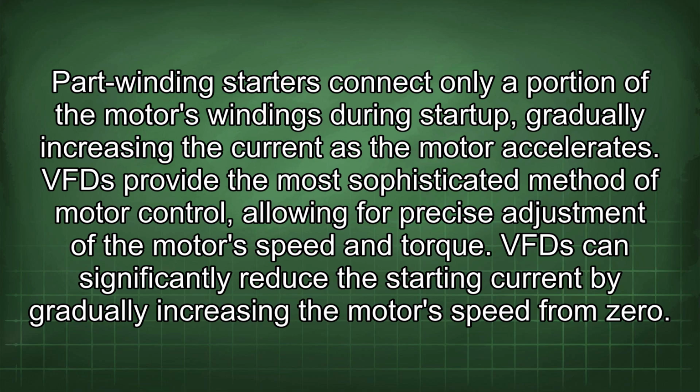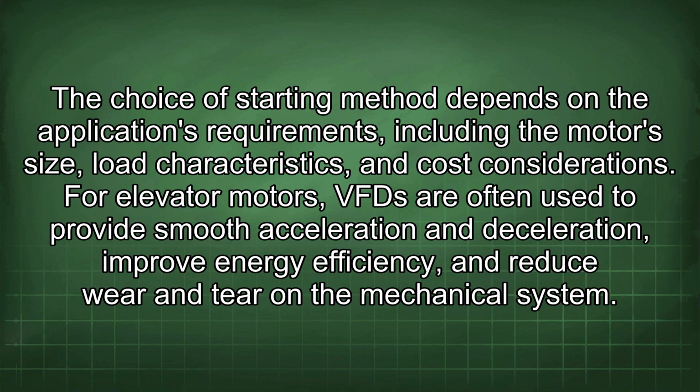VFDs provide the most sophisticated method of motor control, allowing for precise adjustment of the motor's speed and torque. VFDs can significantly reduce the starting current by gradually increasing the motor's speed from zero. The choice of starting method depends on the application's requirements, including the motor size, load characteristics, and cost considerations. For elevator motors, VFDs are often used to provide smooth acceleration and deceleration, improve energy efficiency, and reduce wear and tear on the mechanical system.